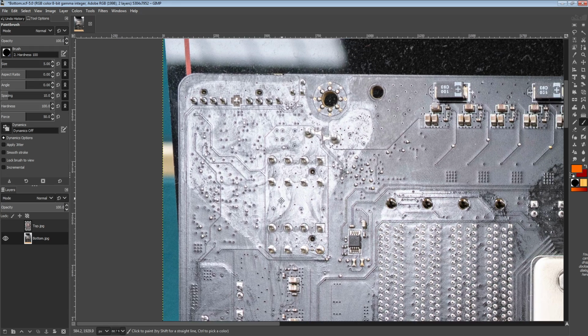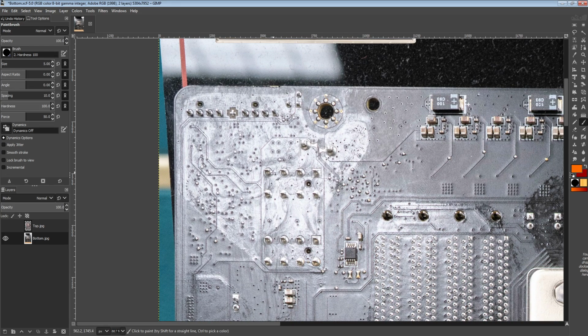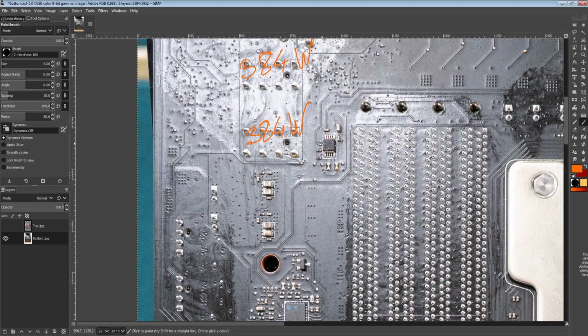That basically means you're only looking at like 384 watts power capacity per connector here. And I think they should have gone for the solid metal pins, just because that alone would bump you up into like the 480 watt range.